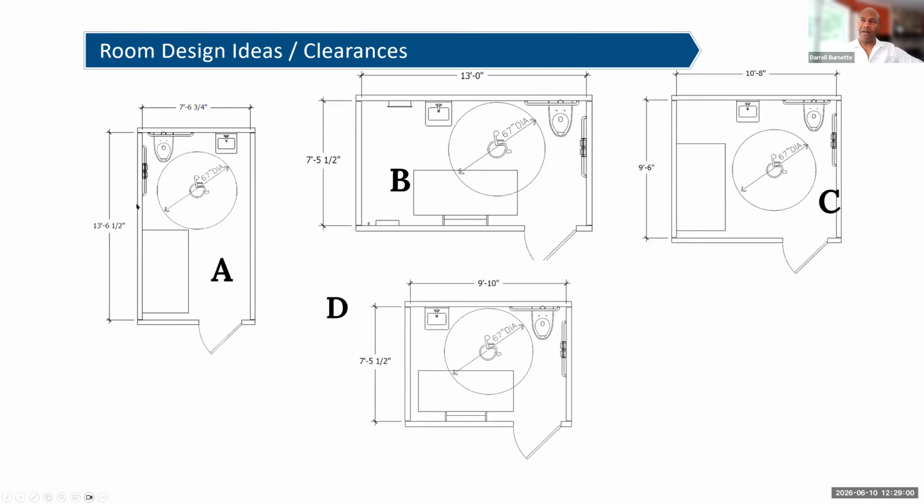But with these required grab bars around the toilet, unless you have a really big space, it's difficult to put the table near the toilet. It may encroach on that grab bar. So sometimes if you are designing from scratch, it's usually recommended or better to put the table near the sink. That way you don't have as much to involve with the clearance with the grab bars on the toilet, because those grab bars are required as well. Yes, the transfer space is always something to consider there, right?